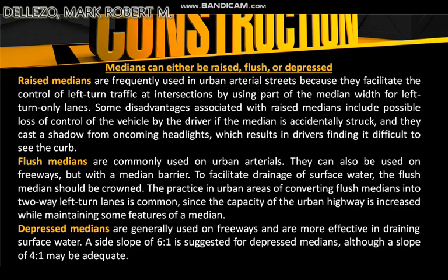Depressed medians are generally used on freeways and are more effective in draining surface water. A side slope of 6:1 is suggested for depressed medians, although a slope of 4:1 may be adequate.